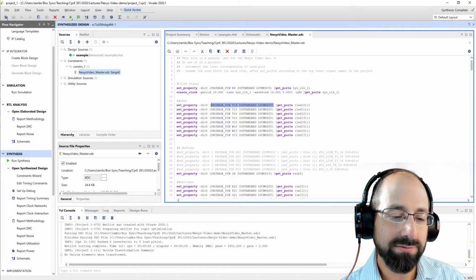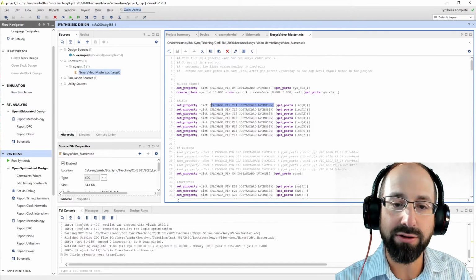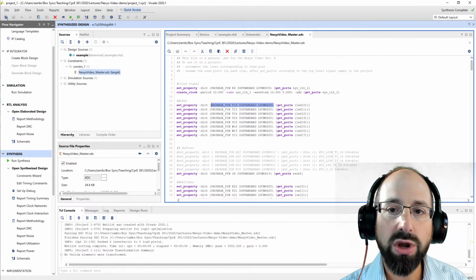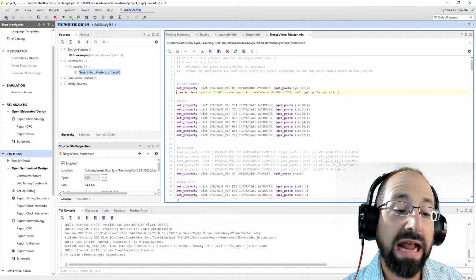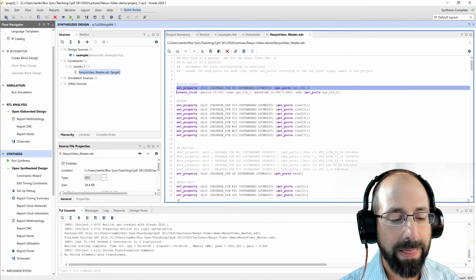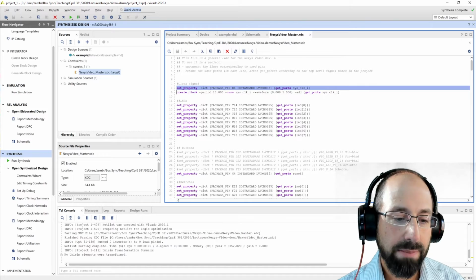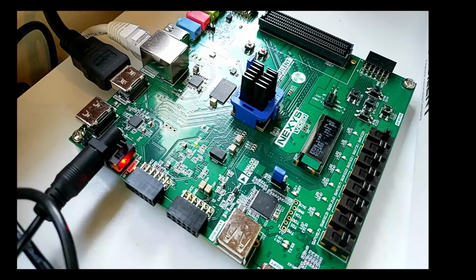Why T14? The engineers at Digilent put it there. There's no other answer for it than that. There's no magic to that other than that. We also can set a lot of other properties for the design as well. A very common thing you would also set would be, well, I have a port called clock in my design, but that is also generally a physical thing. Somewhere on this board, I don't know where, there's an actual clock oscillator circuit that is generating, in this case, a 100 megahertz input clock to the board, or to the FPGA specifically.